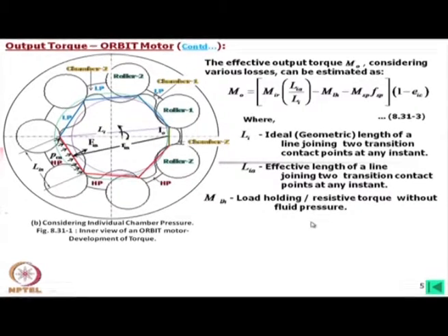This means that we need a torque to start this motor without any load, that is the load holding torque. On the other hand, this load holding torque can also be named the starting torque required. Now, obviously this increases depending on the fittings. If the fitting is too tight, this part will increase. That can be estimated also. This is normally found out from experiment.